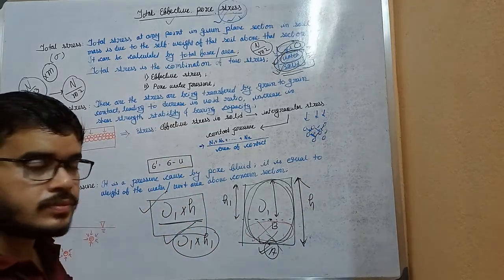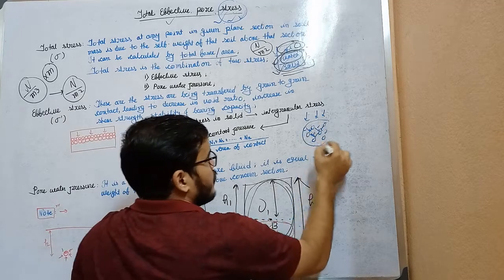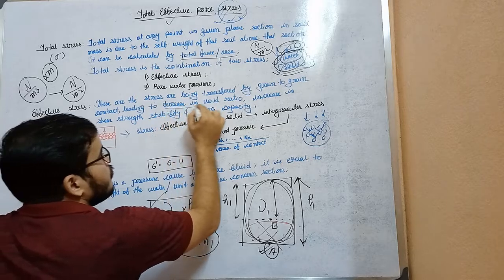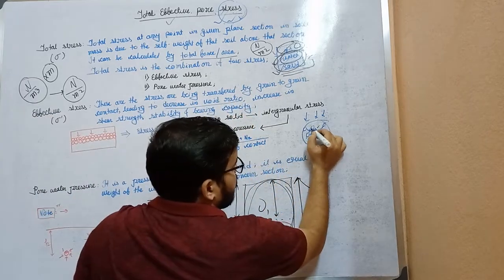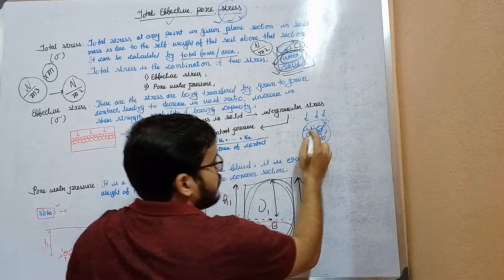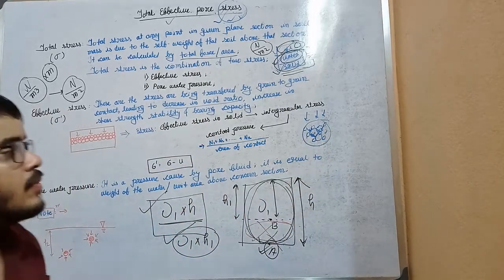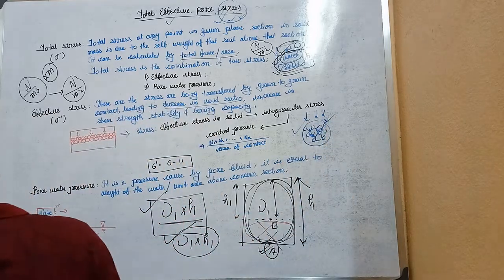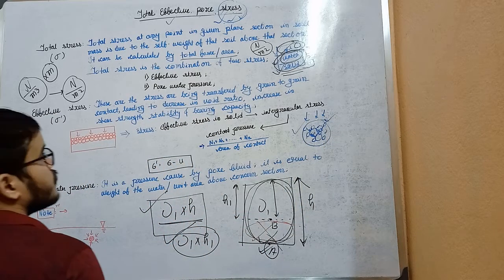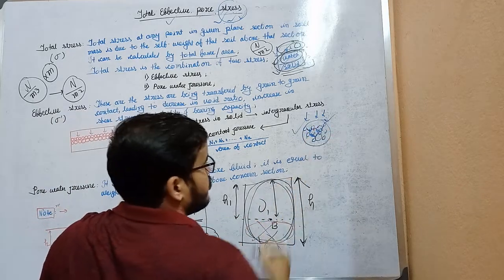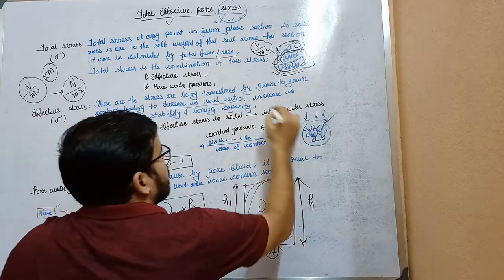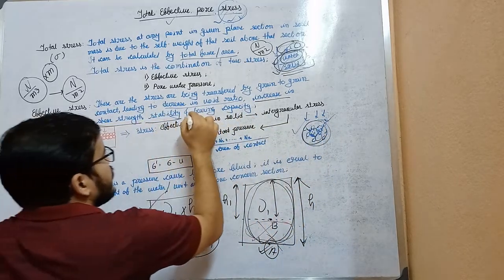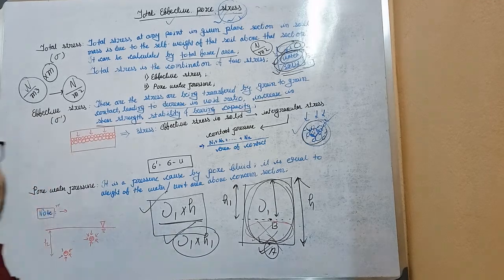As they come closer, the denseness will increase and the void ratio will decrease. That means the space of the voids decreases as the grains come closer to each other. Due to coming closer, the soil will increase its shear strength, stability and bearing capacity.